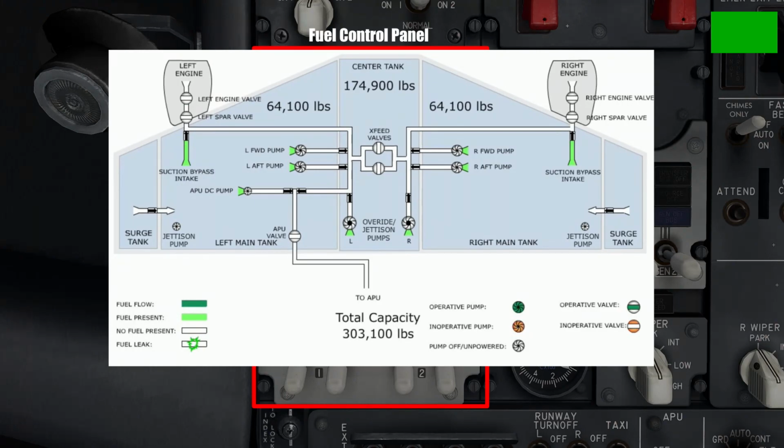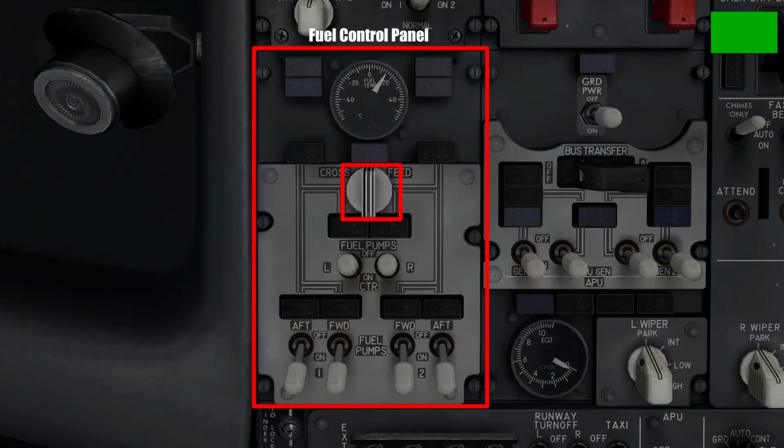However, in the unlikely event that fuel is being drained unevenly from the 2 wing tanks, for example, the left tank is draining at a rate of 800 gallons per hour and the right one drains at 700 gallons per hour, this crossfeed valve may be turned by the pilot so that the fuel is shared between the 2 tanks. This can help prevent any problems with the weight and balance of the fuel, causing problems with the flying characteristics of the aircraft.